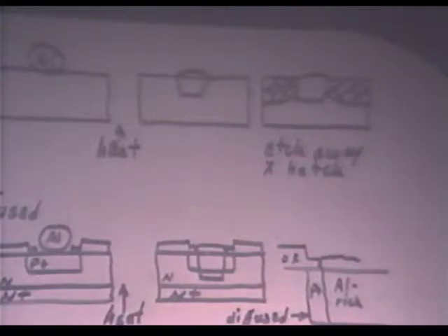That's fine, but it leaves you with the junction exposed to the outside world. Some people put organics, varnishes on there to protect it. TRW claims that they are making their LVA series with an inorganic passivation on there. I can't argue with it. Don't know how they do it.